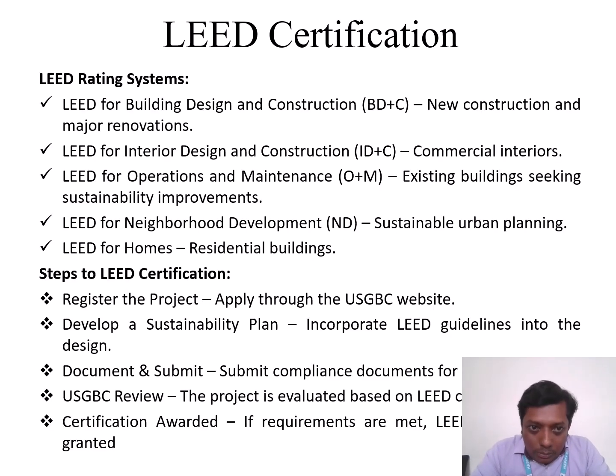LEED rating systems. Mainly LEED for building design and construction, LEED for interior design and construction, LEED for operations and maintenance, LEED for neighborhood development, LEED for homes. That means residential buildings. Steps to LEED certification: first research the project, then develop a sustainability plan, documentation, and we are going to submit the documents to USGBC for review. After that, the certification will be awarded.